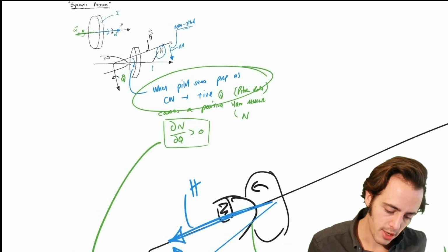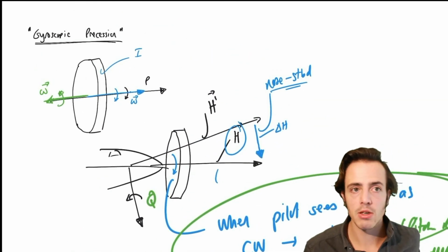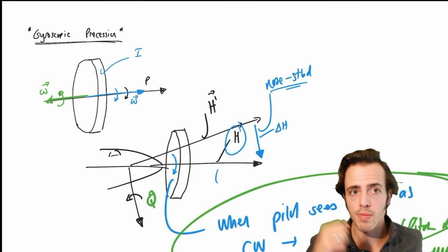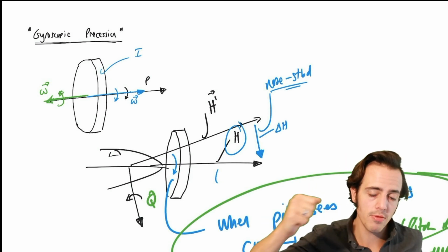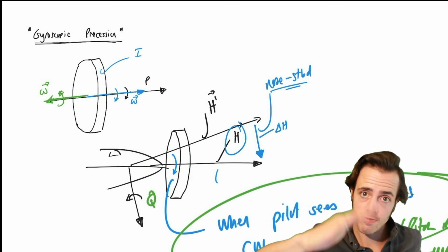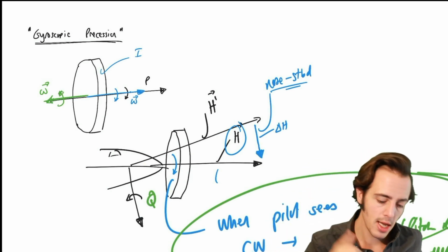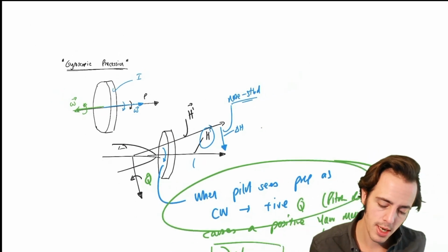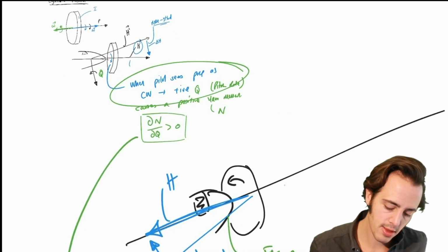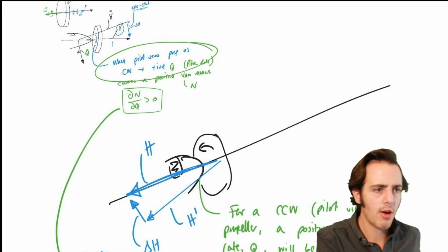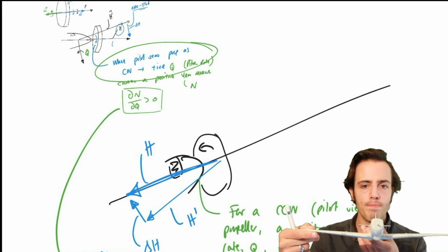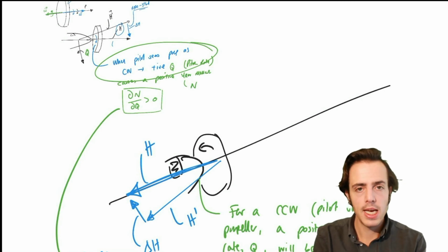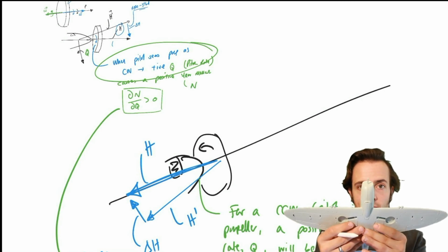And then I thought I'd confuse things even further by bringing up this idea of gyroscopic precession. If you haven't seen a demonstration of someone holding up a bicycle wheel, spinning it round on a piece of rope, and seeing it, rather than fall down to earth, spinning round, I advise you heavily to go to YouTube and look up one, because you'll understand this more. And then we said there's now going to be a cross-coupling. If our aircraft has a propeller at the front, or a gas turbine somewhere on our aircraft, if it has a tendency to pitch up, it's going to have a tendency to yaw.